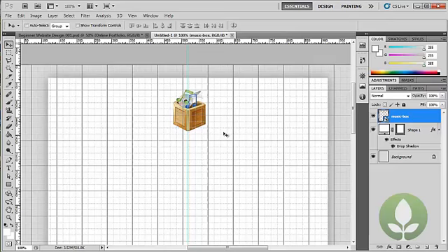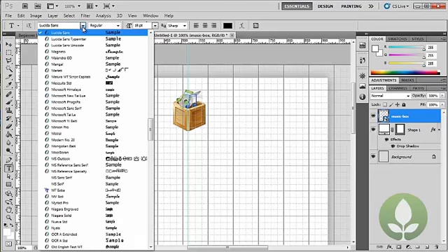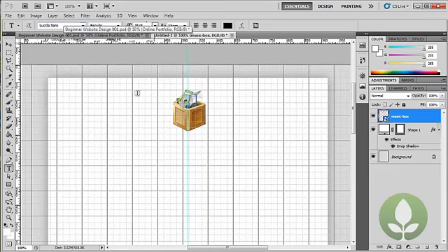Right, now we're going to do some text. Okay, so click on text, and the color that we want is black. The size we want is 18 pixels, and the font is Lucida Sans. Now everybody has that, and it's a web safe font, so it's something that we can use with confidence. Alright, now the color is black here. That's the most important. Even though the color down here is white, the properties of this tool is black, so that's the one you believe.